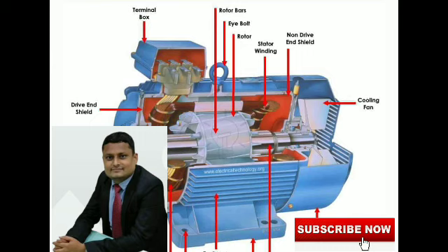Now we will come to the next topic, shape and size of the stator conductor. It can be rectangular, it can be circular. AS less than 5 mm square for circular conductors. AS greater than 5 mm square for rectangular conductors. For rectangular conductors, the width to thickness ratio must be between 2.5 and 3.5. Standard bare sizes of round and rectangular conductors are taken from standard tables.